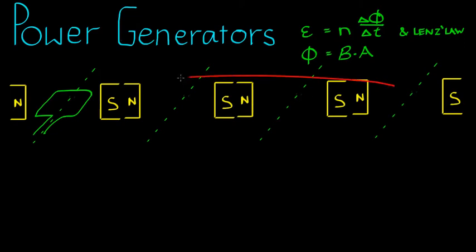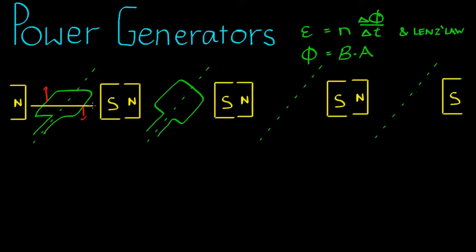So going back to these pictures down here, the first image of the motor, if we push it this way, and we end up with a motor tilted up as we saw before. If the magnetic field lines here are running parallel to the area, pretend they're just scraping the surface of these two wires here, the flux for this first picture is equal to 0. Or in other words, that area in the loop doesn't collect any of those magnetic field lines.